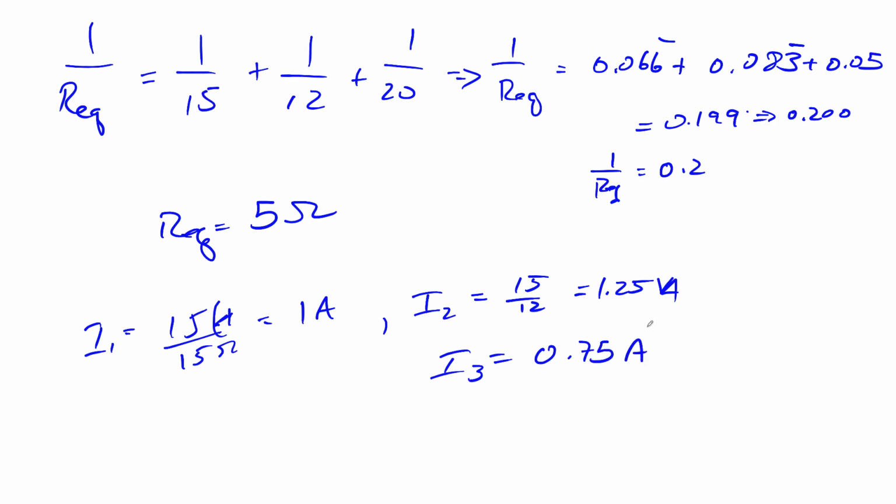And so the higher the resistance, the lower the current, which is what we got here. And the total current, I total, through this set of parallel resistors is going to be 3 amps. And this is how this works. So this is a way to get everything going through, and that matches. We go V total 15 over 5. That's going to give us 3 amps. So those 3 amps get divided into each of these 3 resistors like this.